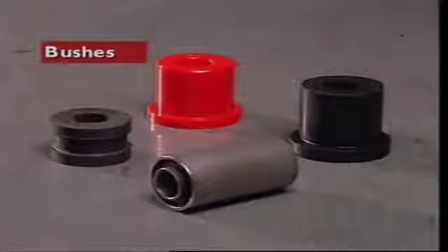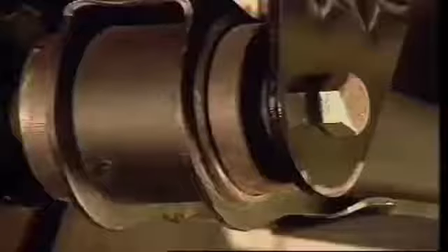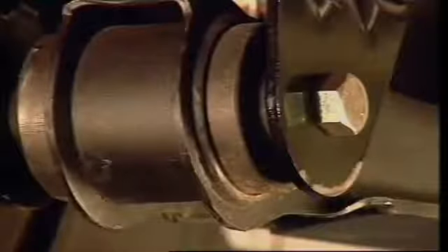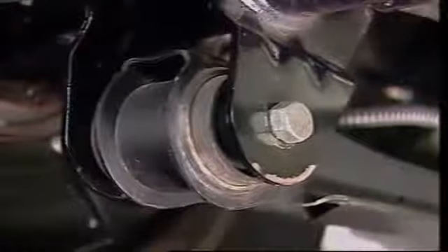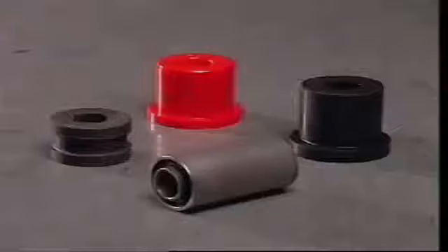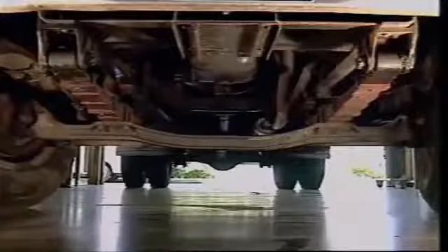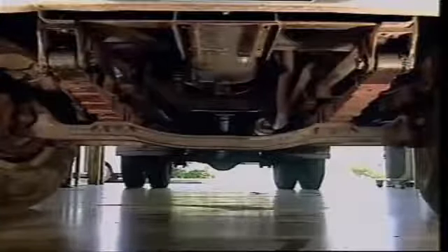This section examines suspension system bushes. Bushes act as bearings at suspension fulcrum points to allow for movement of the component while maintaining its alignment. They can be metallic or made of rubber, nylon or urethane. In commercial vehicles, metallic bushes are commonly used as shackle bushes for leaf springs.